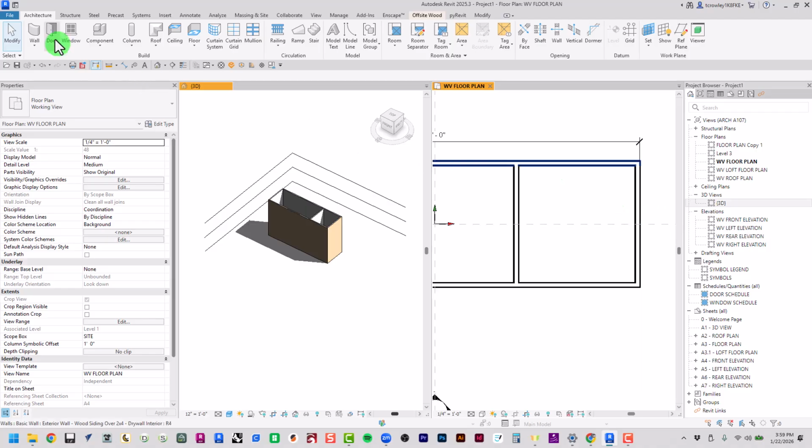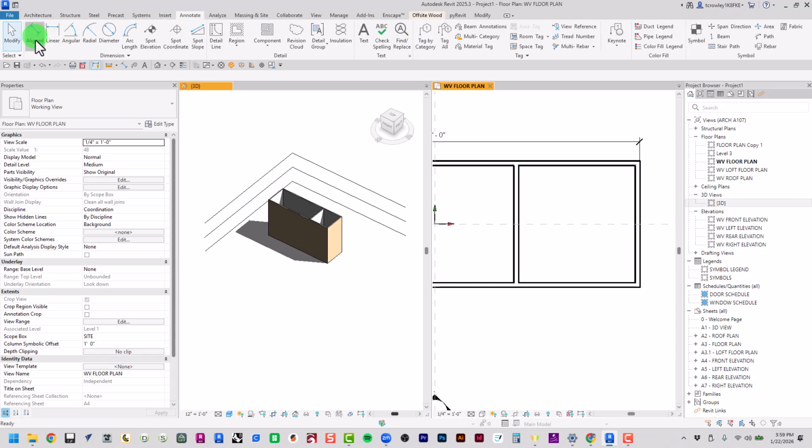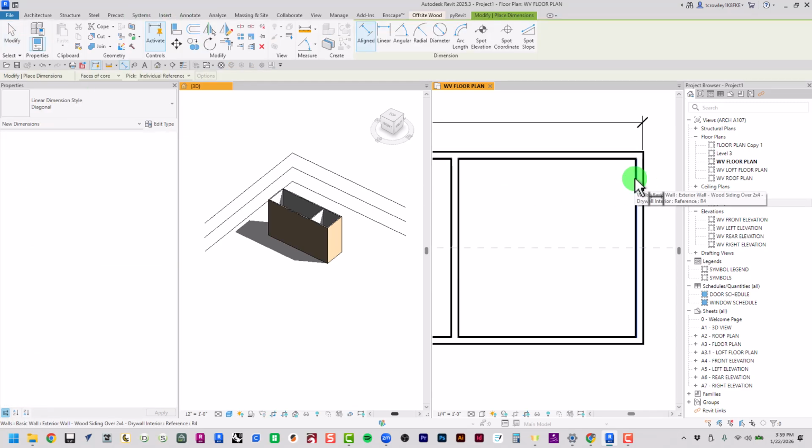So if we have this home on a foundation, that concrete pad or stem walls, the dimensions of that thing pretty much tell us the dimension of the structure of the framing of the walls above it, right? And then any of the finished materials are kind of arbitrary, right? They actually vary in thickness. As far as construction documents go, we're not really concerned about the placement or referencing the finish wall dimensions. We're more concerned about understanding where the structural components of the wall go.